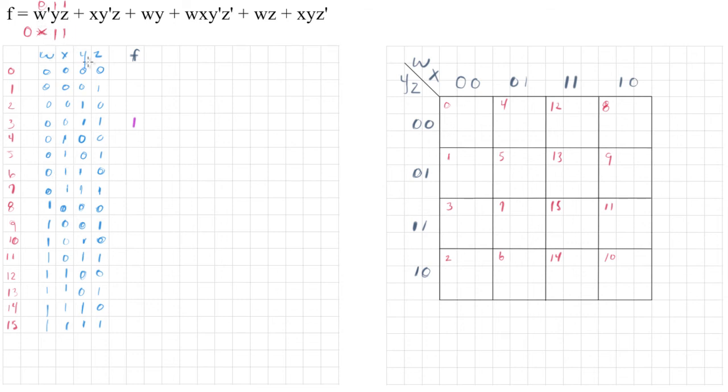And we're looking for 0, 1, 1, 1. So 0, 1, 1, 1. That's the 7. To give you a preview of what I'm doing here, we have the 3 and the 7. So over on the K-map, those are going to be marked as on. And we're going to go through and do that for the rest of the expression here.